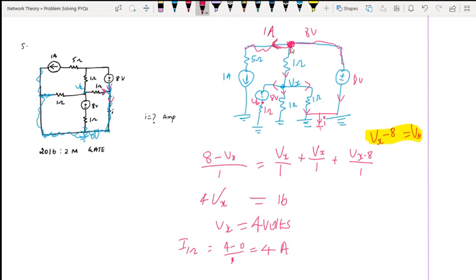If I know the downward current, I can find the current here. So let me write the KCL for this point, let me call it VP, just for naming. At VP, we have 1 ampere leaving current. I'm assuming everything to be leaving current here. So entering current is 0. So 0 entering current equals all the leaving current. One is 1 ampere. The other, the downward current, with VP equal to 8 volts, is 8 minus Vx, where Vx is 4 volts, divided by 1 ohm.